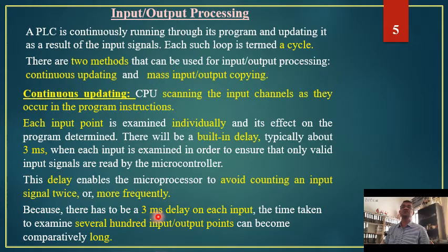Because there has to be a 3 millisecond delay on each input, the time taken to examine several hundred input output points can become comparatively long. I gave you the example of 1000 sensors and the amount of delay that has been encountered there, something like 3 seconds.